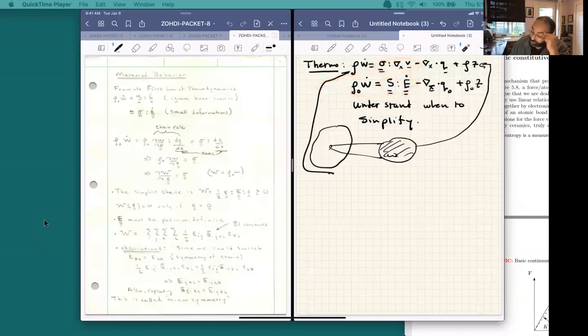We then have the divergence of the heat conduction, and of course we have the value of the heat flux. The heat flux in the current configuration is Q, and in the reference configuration it's Q0. I suggest that you look into the notes, as I asked you to go through the derivations, to understand what the differences are between Q0 and Q. They're very minor. One is the product of F times Q times the Jacobian, and it comes from this whole concept of the Nanson formulation. Nanson, of course, represents how things are balanced back and forth between those different configurations.